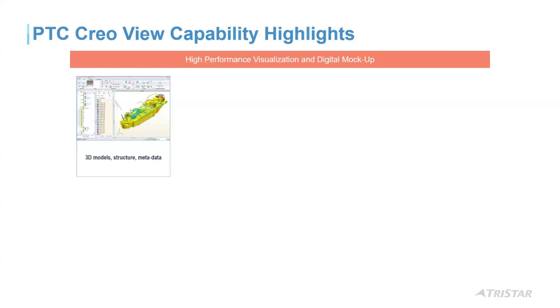For administrators, there's also a way to simplify the menus. So if you don't want people to have access to the measurement functionality, in the Creo View MCAD license, people can actually start converting. So if they open up a Creo model, they can start converting to STEP files or converting to a 3D PDF or something like this, that they can then use for something else.